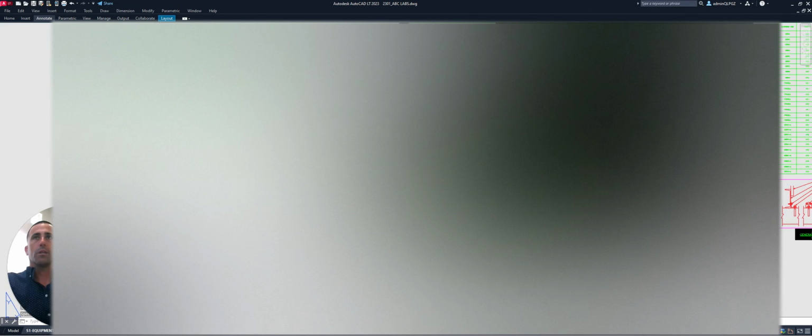Alright, so first of all, wind design data. So wind design data is irrelevant, right, because it's interior. So we say interior non-exposed risk category, and then risk category is 2. The seismic information is the information that really matters here. So based on that sheet that I printed out earlier, the SS value was 1.938. So we'll just go 1.94. The S1 value is 0.713. So we'll go 0.71. And SDS is 1.55.